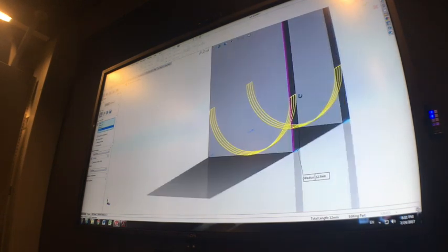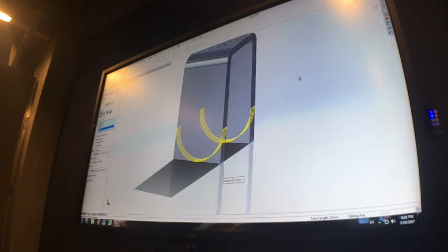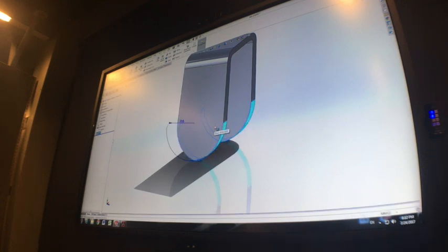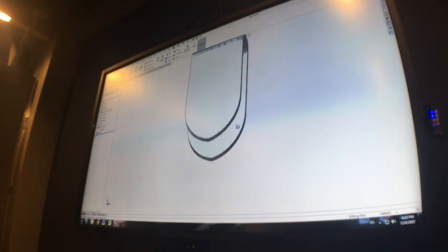This is a perfectly fine way of creating fillets for this purpose on this shape. When you're happy with the size, just press OK, and that fillet is a feature in your feature tree, which you can click and change the dimension of. If I change that dimension up to 15, you can see it's now left another sharp point at the bottom, because the 12.5 doesn't fit.